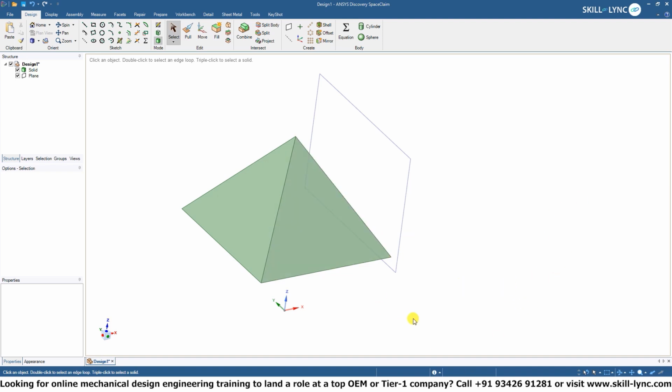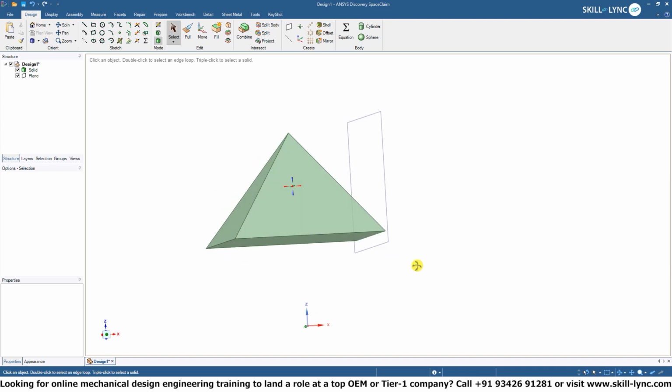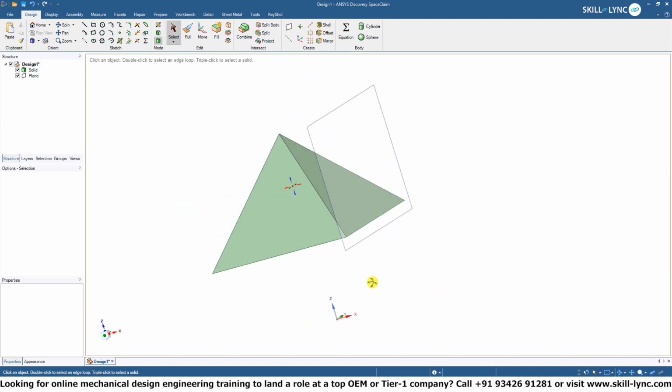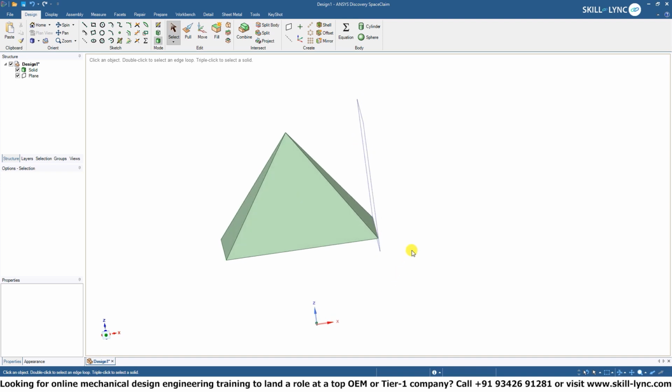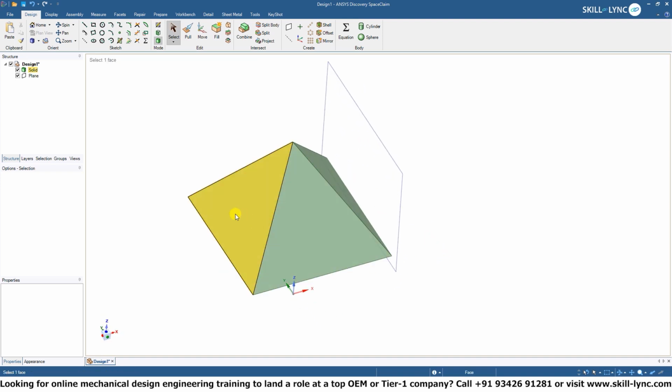As you can see, previously I attempted to get by using the surface of the pyramid itself to do the extruded cut on the sides. However, that didn't work 100% as I would have wished. So I had to change my technical approach, right? I had to ask, what is actually resulting in this edge over here being slanted? What angles are actually affecting my extruded cut?